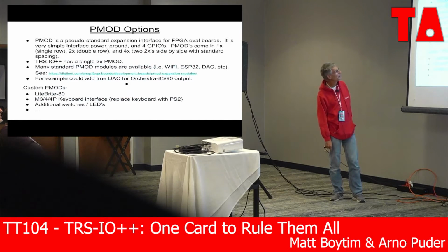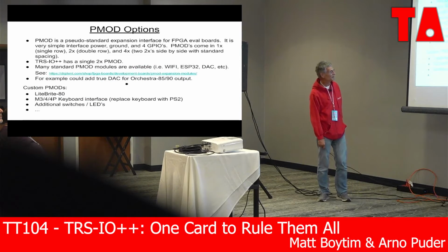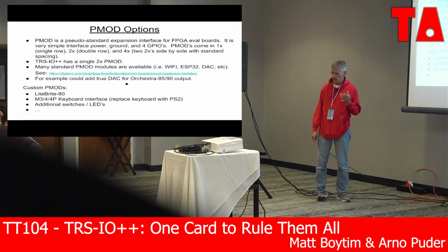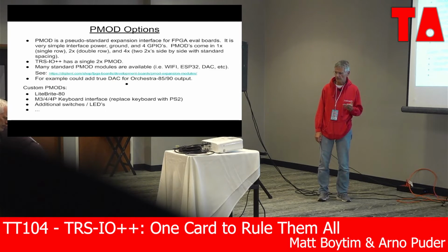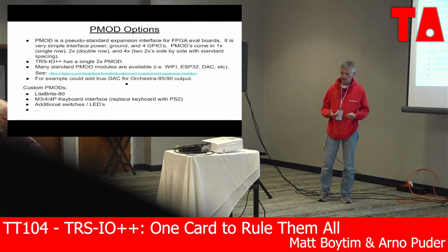Next. So as I mentioned, one of the features is that we have this PMOD connector. The PMOD is a pseudo de facto standard for FPGA modules, and it's real simple. It's power, ground, and 4 GPIO pins. But it comes in 4 different flavors. You get a single, a 2X, or a 4X.